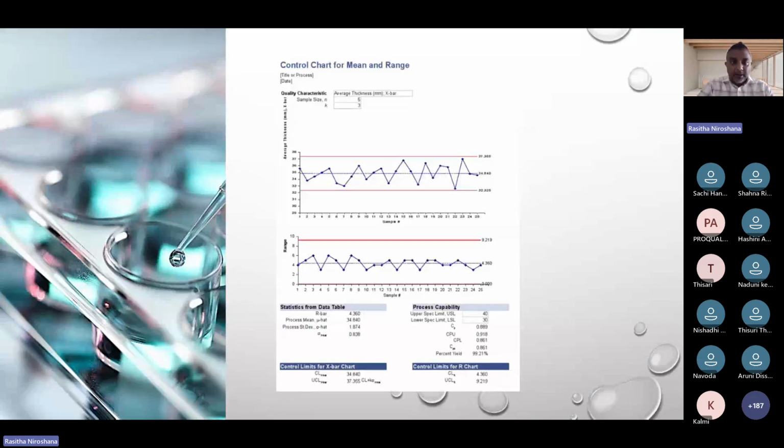I believe control charts and mean range are crucial, because when they go for the ISO 17025 audit, you need to show that your people can demonstrate reproducibility as per the control charts. So this statistical analysis has to be there. You have to be careful about two things. One is the control charts, and the second is the error factors in your organization that you are facing. This is a very important part.